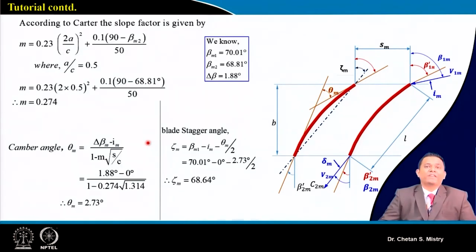Now once we have decided that, this fan we are talking about is a low pressure fan, and we are not expecting it to be an expensive one, and we are not looking for running that fan in a variable speed configuration. Maybe rarely, but it will be rotating at a constant speed. That's the reason, if you look carefully, this blade we are making will be made by bending of a plate. This is what the blade will look like. It does not have an aerofoil shape.